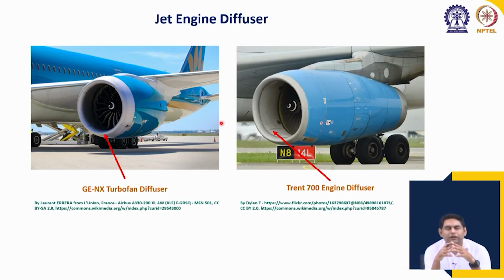Okay. So, we can reduce the workload of the compressor, we can reduce the number of compressor stages by converting this high speed air, or the kinetic energy, to generate a large pressure ratio depending on how much the speed is. So, for very high speed aircraft it can be even larger, and there are experimental aircraft where the compressor is not needed at all, okay, like ramjets or scramjets.